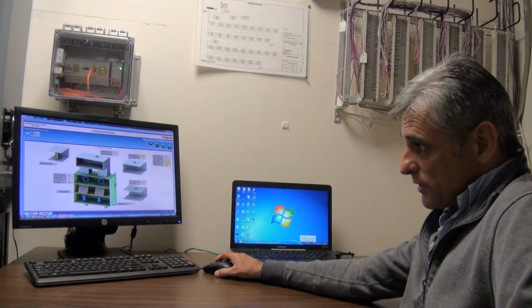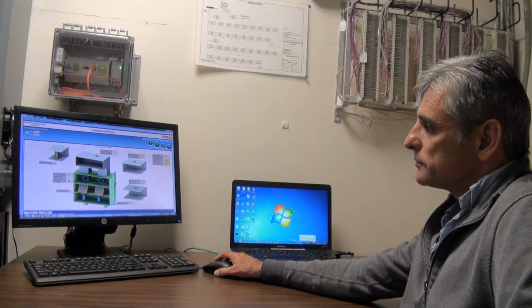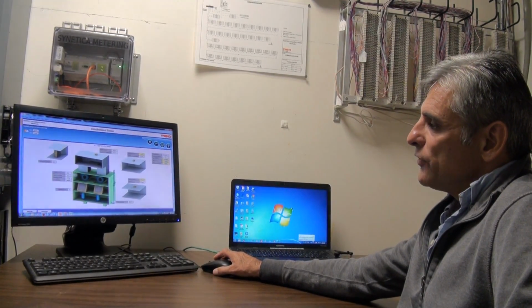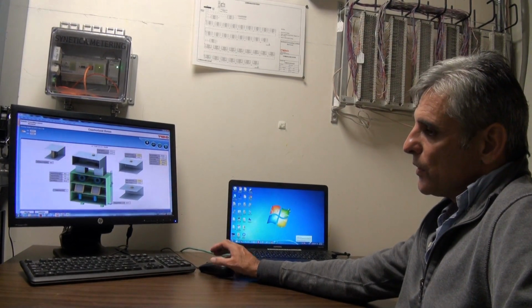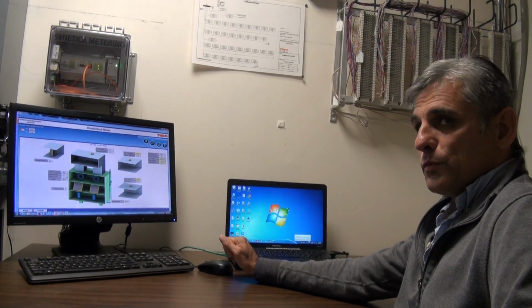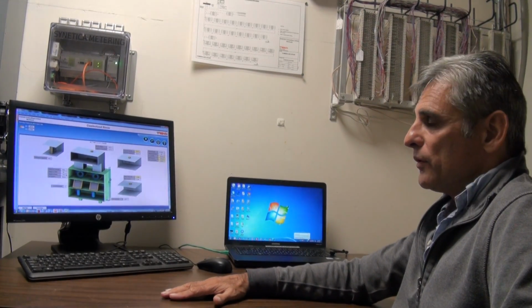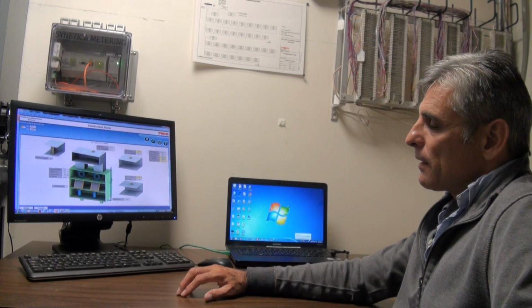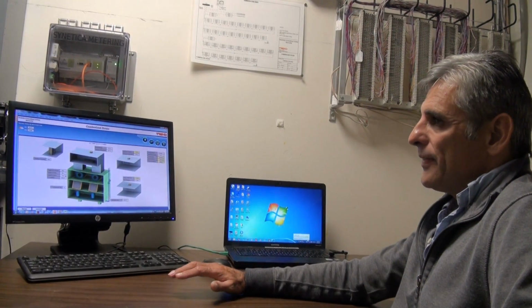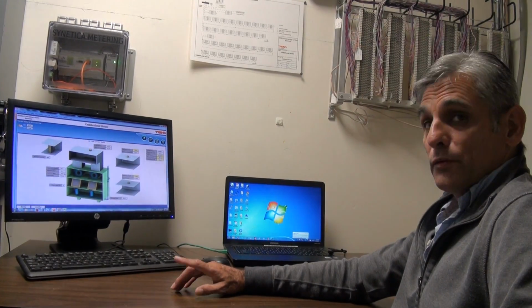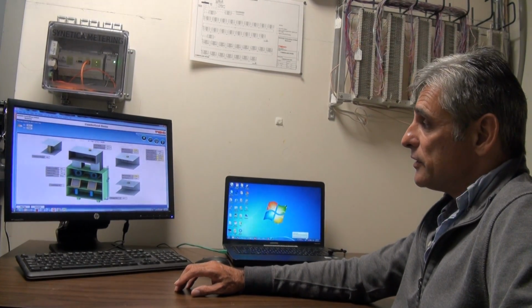See, the fan speed's gone up to 70% again. And before, these fans would just switch on 100%. Now we're actually staging them on. They ramp up very slowly, and that in itself is saving anywhere between 15 and 30% of energy on the motors in this unit.